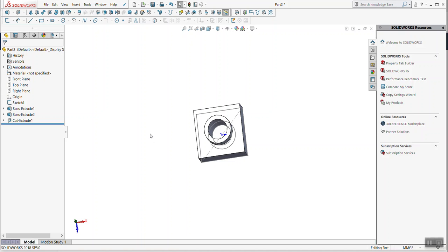It's also something that, if you're working with someone else, you might get feedback on. So anything that you anticipate to change a lot, if you can put it lower in the tree, the better the chances are of having a robust rebuild. The reason is, let's say you have a client and they say, you know what, we don't know how long we want this handle to be on this microwave. You might put the handle build at the very bottom of the tree, because what you don't want to happen is if the handle's at the start of your microwave build and then you base the door off of it somehow, just through relationships in SolidWorks, if you then have to change that handle, everything below it might fail.